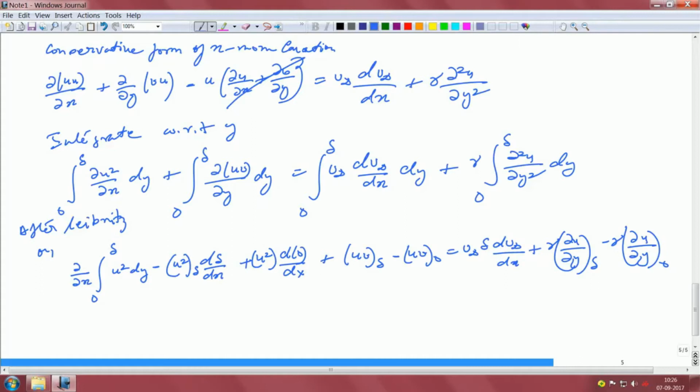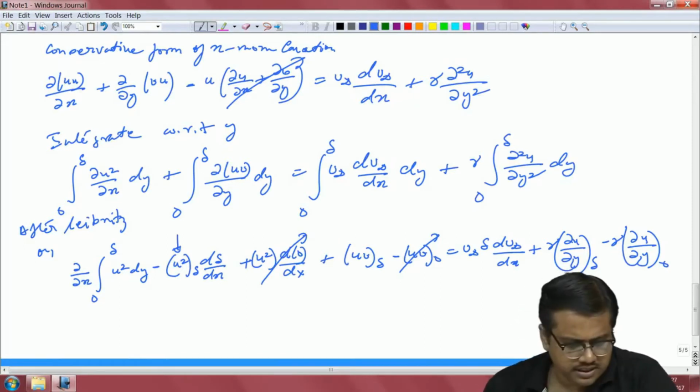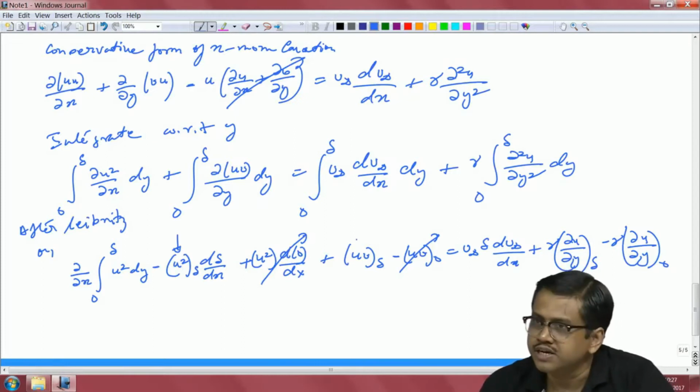Okay. If you take your pick, say for example, few things to note, what is u square at delta? That must be u infinity square, right. U at delta is actually equal to u infinity. Similarly, this particular parameter obviously will go to 0, we know that for sure. U v, whatever is the nature of v, even if there is suction or blowing, u is equal to 0 always. So, that should go to 0 at the same time. Of course, this parameter will stay depending on what you want your u v to be, or will it stay, we will see to that in a little bit.